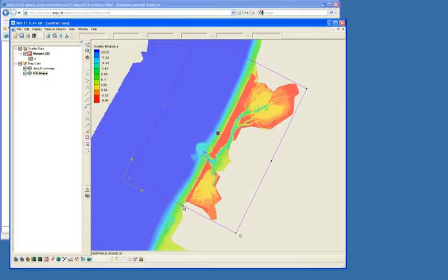The reasoning for starting all of your grid frames for the wave grid in the open water is because of the way the wave model works. Basically it starts at the point of origin on that last row, and it starts marching in one row at a time and working through the energy and the depths and changing the periods and directions and the intensity of the waves as it marches towards the shoreline. So it has to know where to start these waves from.